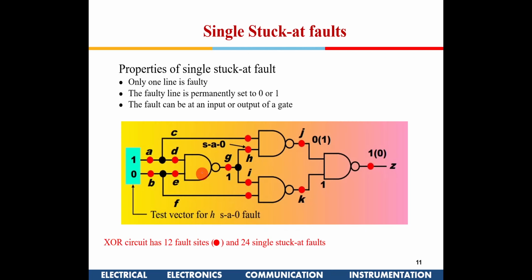No problem. So this is another XOR gate. Now if you see here, this is A. When we do the fault modeling, single stuck-at fault modeling, whenever there is a branching in the wire, we take these three as three different nodes. That means C can get stuck at 0, whereas D need not be stuck at 0. We take those things into consideration because there could be problems with the contacts and things like that.